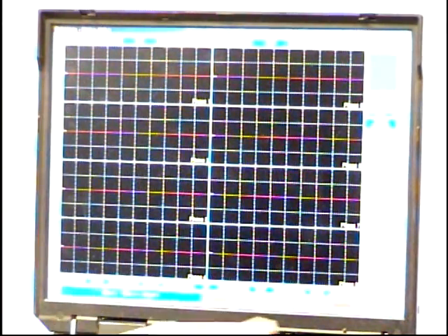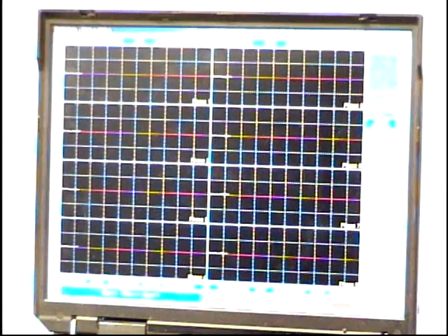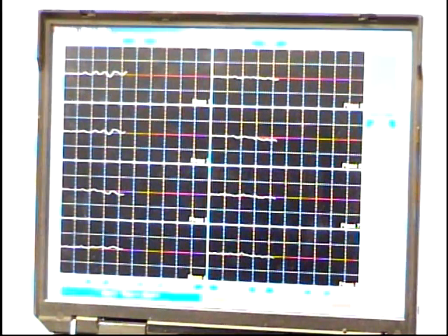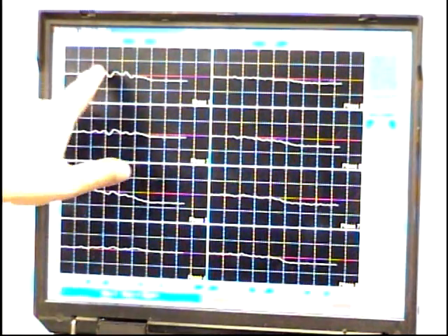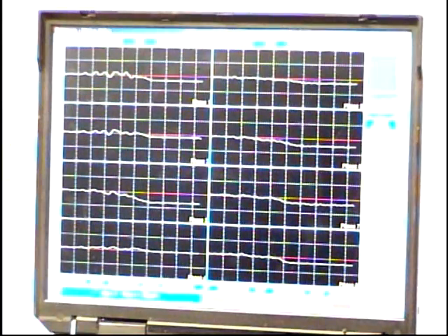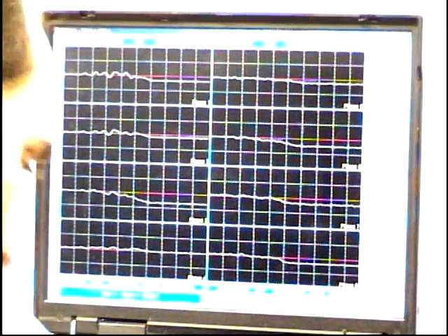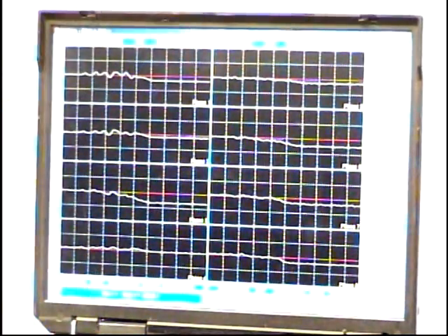I'm going to scan along the length of the tube. You're not going to see any sharp rises. There is a little bit, very minimal. There might be a little bit of wear, and it might just be because of the way I scanned this demonstration. But you're going to see there are no large indications like there were on the other side. That's showing that there is a good tube. Again, approximately 2,500 linear feet.